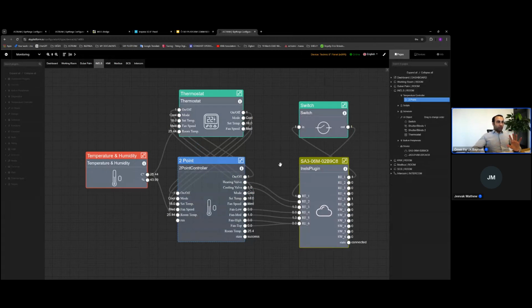According to that, we'll open valves and set the fan speeds. And these are outputs of fan speeds: low, mid, high, and top. I just used 3-level fans. That's why I have limited relays here for this sample. Relay 2 heat valve, relay 3 cool valve, low fan, mid fan, and high fan.